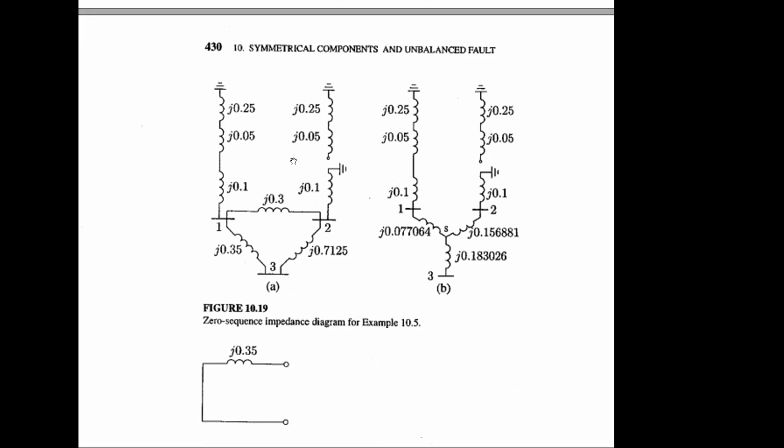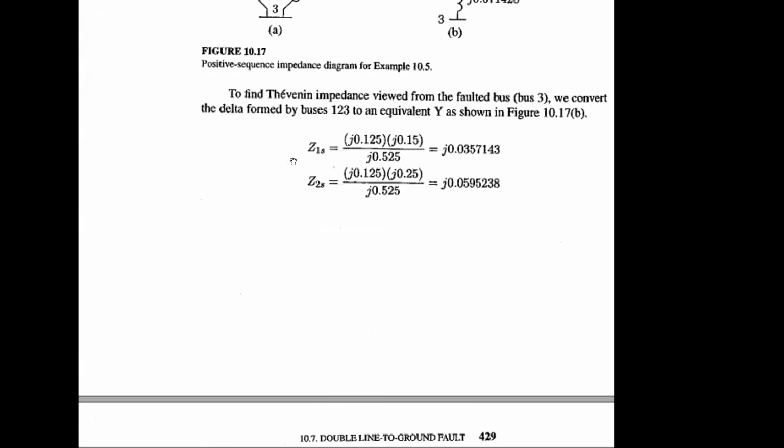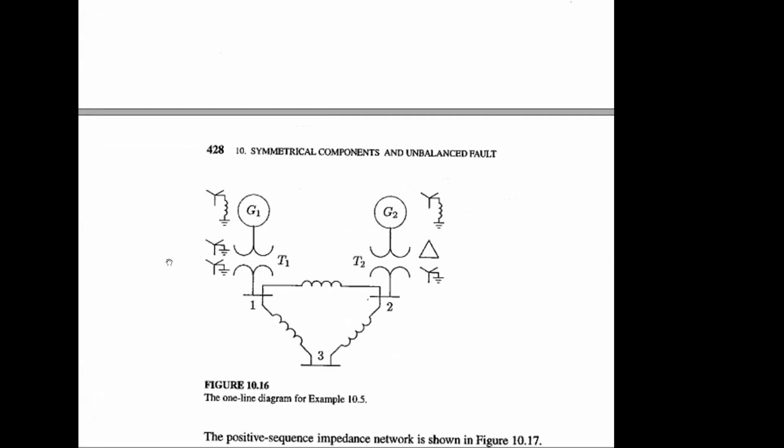Okay, let me clarify simply what you are doing. First step is to consider the equivalent impedance for all the sequence components. Okay, that means Z1, Z2 as well as Z0. If you have been given any circuit, any single line diagram, what you have to do? You have to put the information for different scenario. This is the single line diagram, might be another single line diagram.